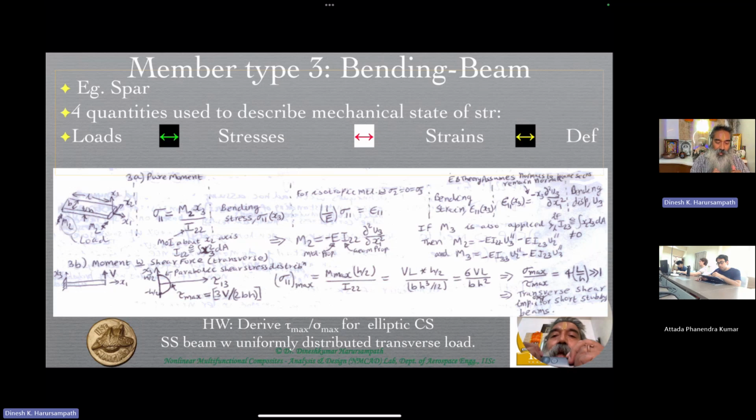So the stress acting on a cross section is not uniform, with some portions under compression and some under tension. Nonetheless the cross section has a normal x1, so the first subscript for the stress will be 1, and the second subscript will also be 1 because it's again acting along the length, even though there is no axial force being applied.